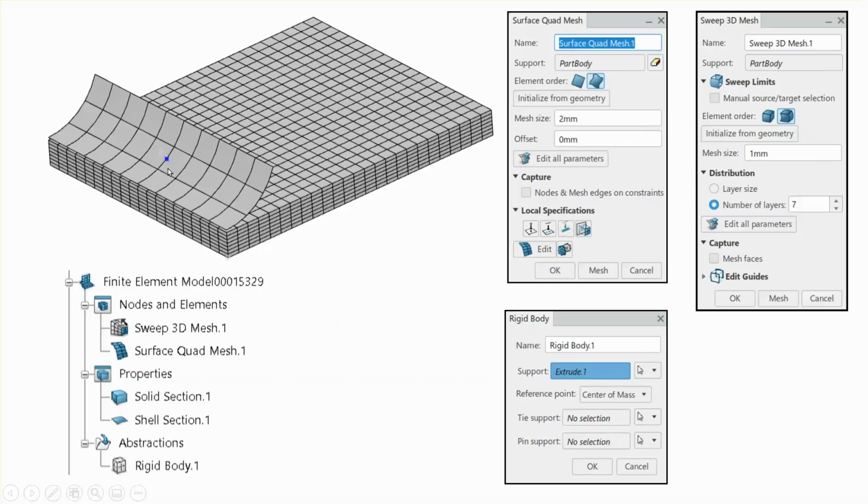So I'm going to apply my displacement and things like that to that reference point. But also you have to mesh it. If you're doing it as a rigid body, you have to mesh that rigid body. I can mesh it, so therefore the material mesh it and declare it as rigid body. Therefore the material properties of the cylinder are irrelevant. Okay. However, I will use the information that's given to me by the reference.